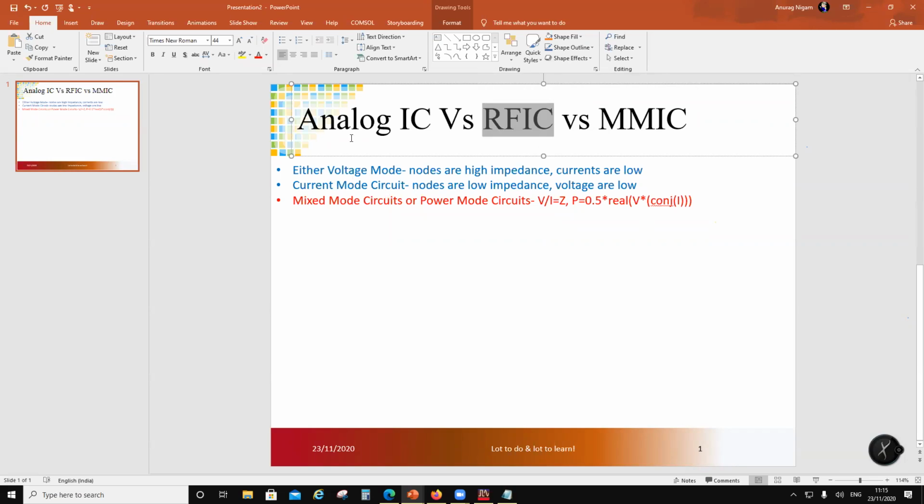Now the question is whether the circuit has to be single-ended or differential. Most of the circuits over here are single-ended, meaning the signal has a ground reference. Even here, the signal has a ground reference. Here, the circuits can be single-ended as well as differential. Now, the circuits are differential for a reason. For example, any single-ended circuit needs a bias point. And if the gains are very large and the bias point is fixed, the gain is only for a very small input voltage range.